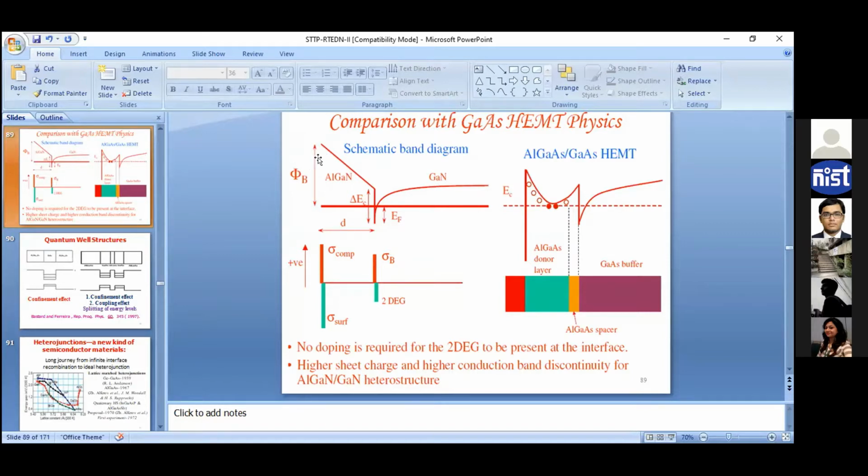Due to the difference of their work function between metal and AlGaN, there is surface charge which appears across the AlGaN, and when we solve the Poisson's equation, this potential will reduce. Yes, that is a quadratic equation as far as I know. That should not be a straight line; there is a kind of bending.